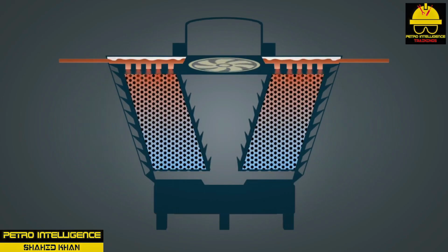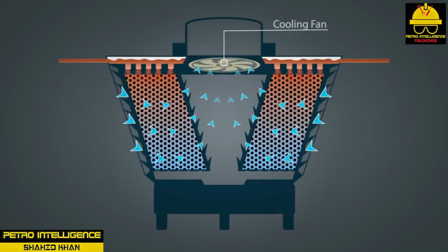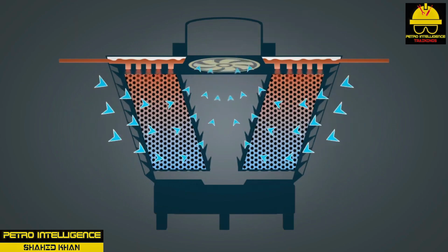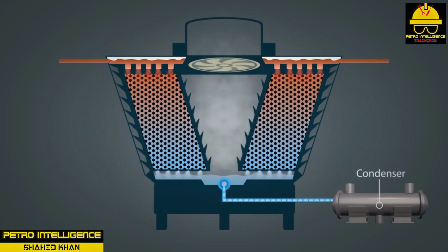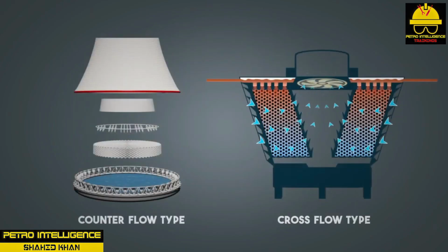There are two ways to measure temperature: dry bulb temperature, dBT, and wet bulb temperature, WBT. Wet bulb temperature takes into account the relative humidity, whereas dry bulb temperature does not. Wet bulb temperatures usually are lower than dry bulb temperatures. The wet bulb temperature, perhaps the single most important factor in cooling tower performance, can be described in several ways. The lowest theoretical temperature to which water can be cooled in the tower. The temperature of the air saturated with water, also referred to as the dew point of air. A theoretical temperature that cannot be reached, only approached.